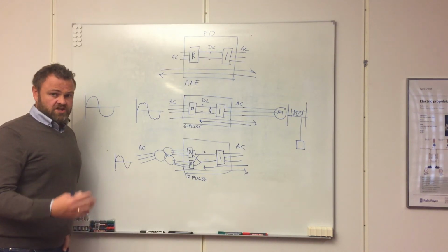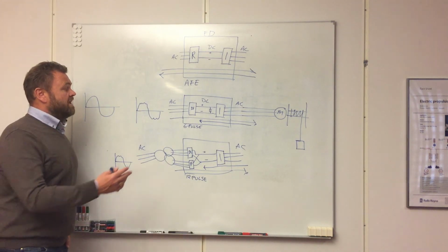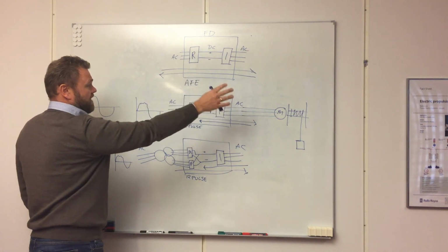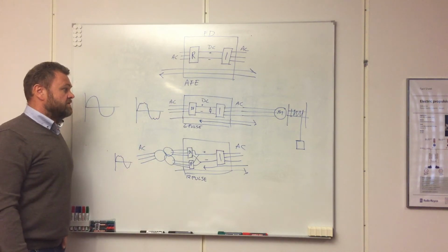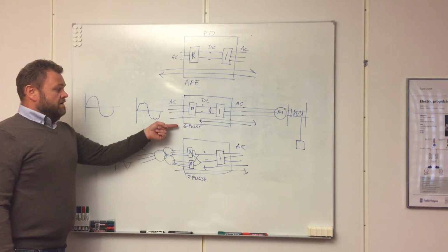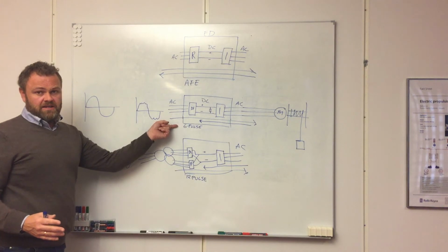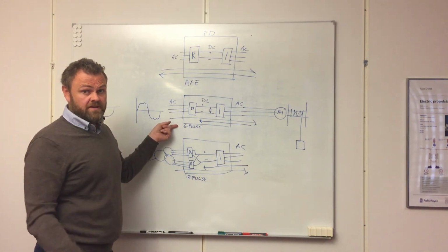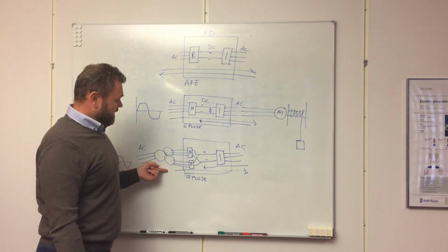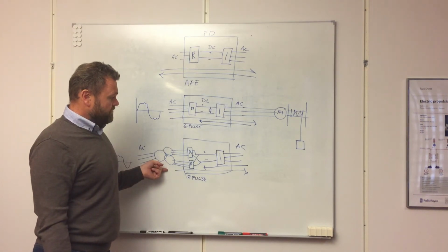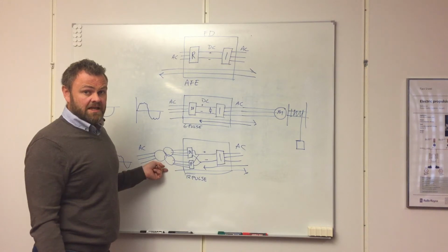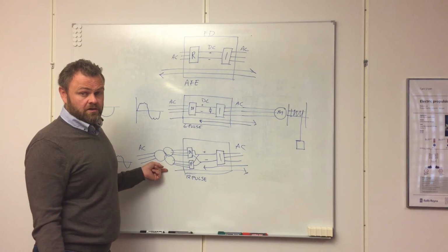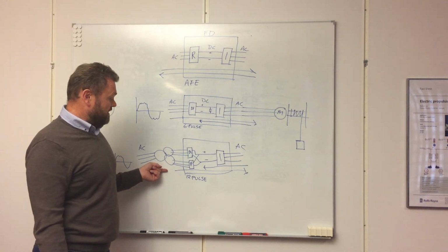We can brake a winch, we can brake the propeller, we can have a generator working as a motor or a generator seamlessly in both directions. 6 pulse, typically in use for smaller fans and pumps on board a vessel. 12 pulse, you have seen that probably in many vessels for main propulsion, for tunnel thrusters and stuff like that.